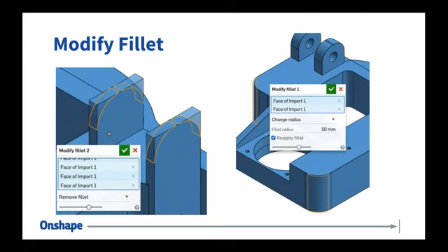The next one is something I think is very unique, and it solves a very common problem, and that is the ability to modify a fillet. Oftentimes you need to make radius changes to models for whatever reason. Sometimes it's driven by tooling, sometimes by cost or some other factor, where you need to change the radius of an imported model. Change the fillet size, for instance.